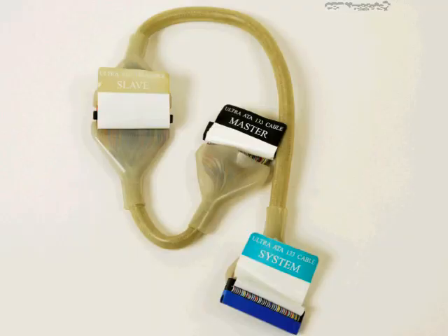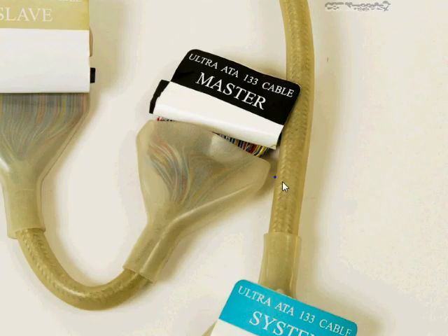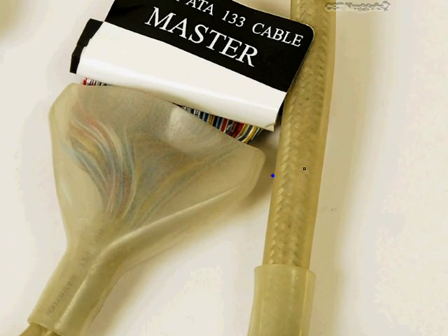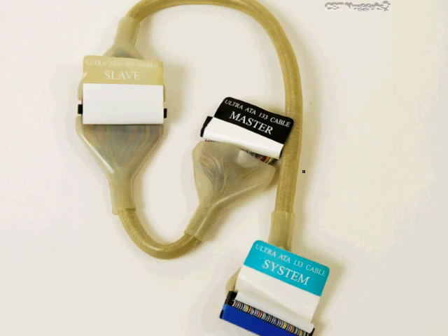Now, the cable I was talking about, we show here by way of example. This is a round cable, although most of them are probably actually going to be flat ribbon cables, which have a tendency to block airflow and are difficult to work with. That's why some manufacturers came up with a round design here, which they have also given additional shielding. If I zoom in here, I think you can see that there's a braided shielding that goes around that, which helps to mitigate the crosstalk that the 80 wire design is meant to help with.